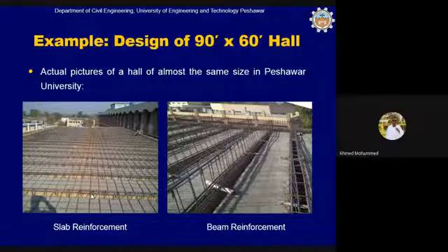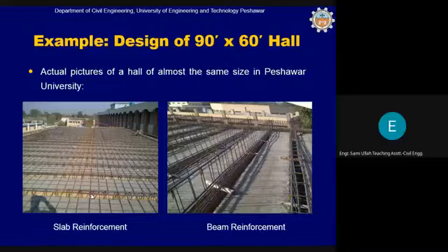No, but the wall, if the slab reinforcement is terminating in a beam, and below the beam there is a wall, then in that case the wall is not integral with the beam and neither with the slab. The wall will more likely be a non-load bearing partition wall in that case. There is no such situation that slab, beam and wall are all integral. It is possible, but only if the wall is concrete.